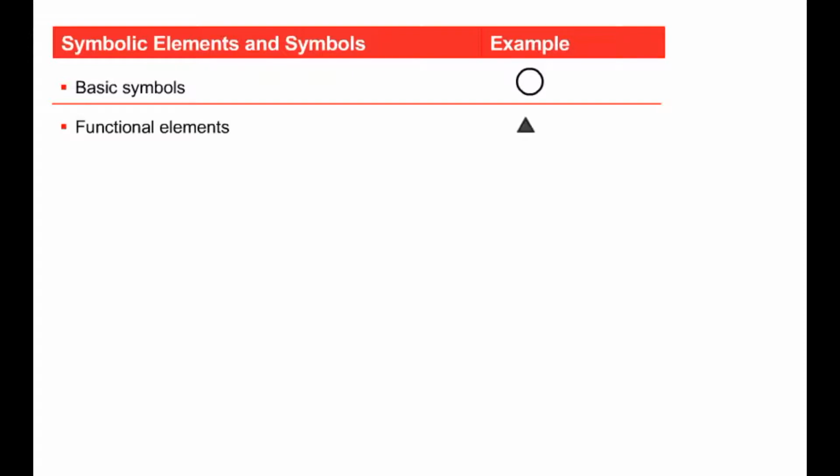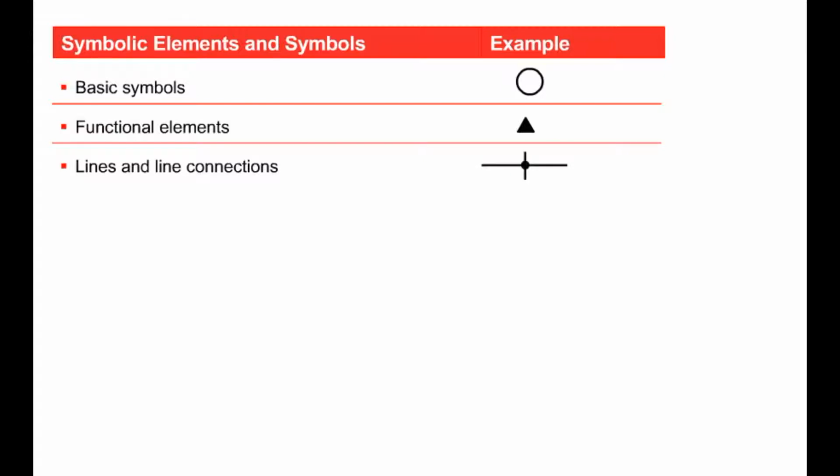For example, a small solid triangle stands for a source of hydraulic energy, while its orientation shows the direction of flow. A circle with a small solid triangle pointing outwards has the following meaning: energy converter from which hydraulic fluid is pumped out. You are already familiar with this device. It's a hydraulic pump. The components are connected together by straight lines, which can cross or join together and may contain connections. The example shows a line connection.